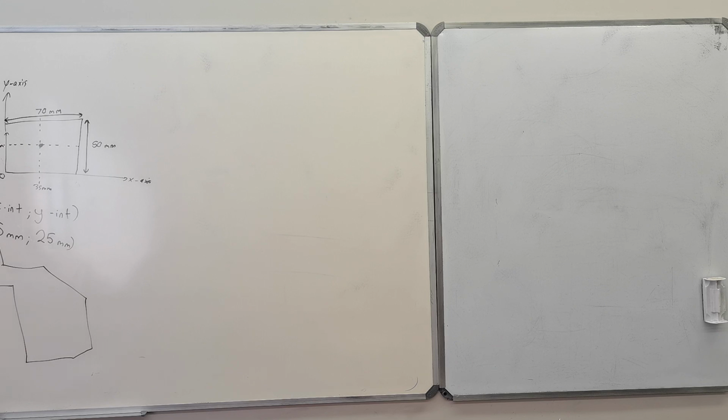Now that can be used for whatever else, but the table example is a nice example, right? So, if you want to know the centroid of a square, look at page 87. Can you see you have your y and x axis? Your square is on it. To get your center points, you will take the distance A and halve it, or divide it by 2. That will give you your x-intercept and your y-intercept. Remember, in a square, all sides are equal. For a rectangle, you will take half the length for your x-intercept and half the breadth for your y-intercept.